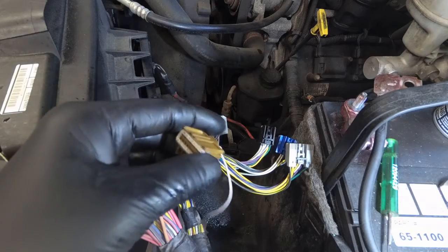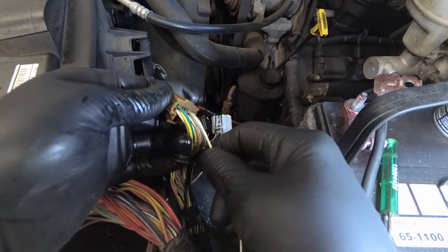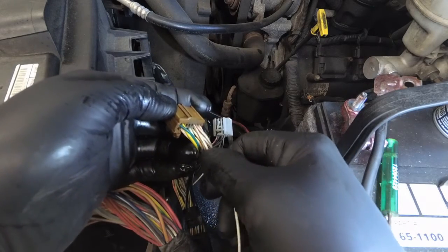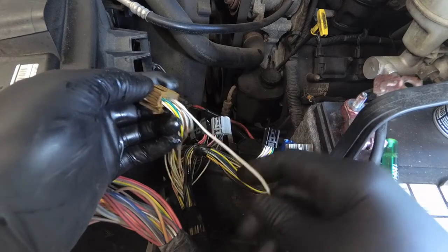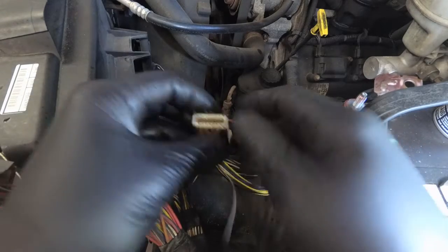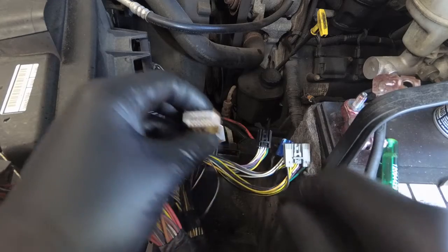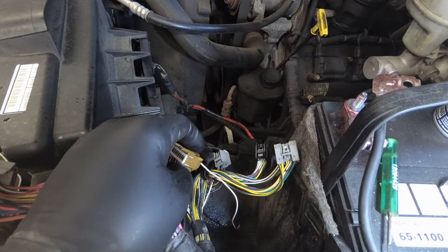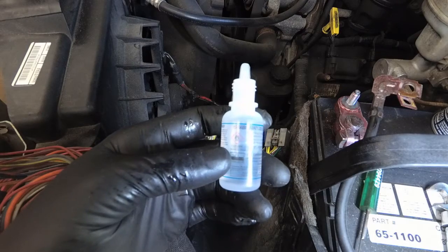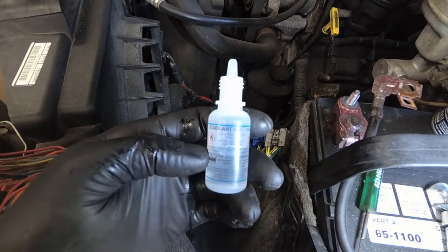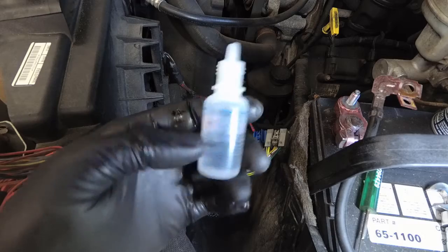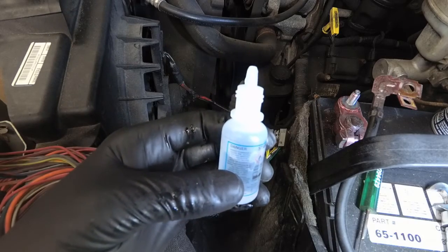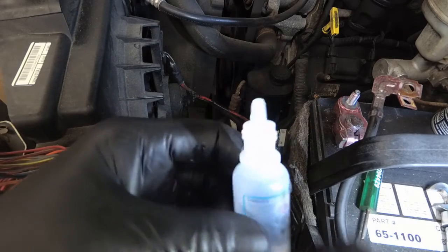Well, that was fun. I literally had to take the remainder of that terminal out of there in powder. So now we're going to splice this wire and reconnect the new TIPM and follow the instructions on programming or setting it up. I've also started using this Stabilant 22A on sensitive connections like these CAN bus wires.